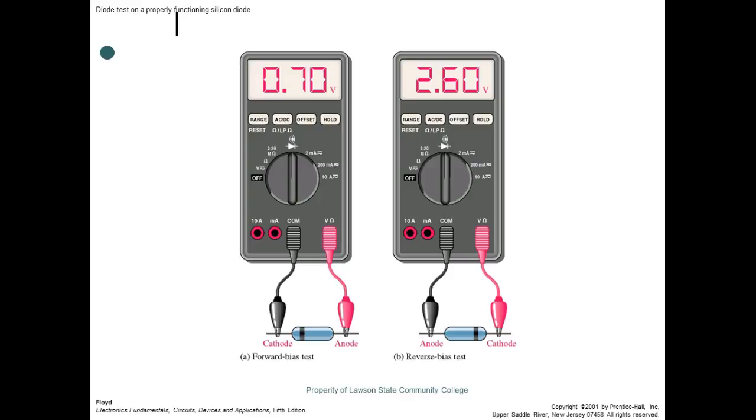If it shows another voltage measurement, that's what it'll get when it's reverse biased. But the ratio is going to be extremely high, right? You understand that? Are we okay? And we showed y'all that you could check it with an ohm meter too sometimes, but on a true ohm meter, we're looking for a real high forward to reverse resistance ratio.